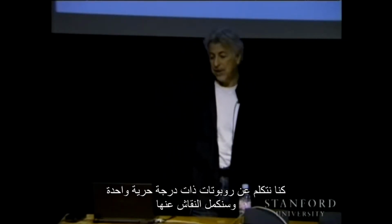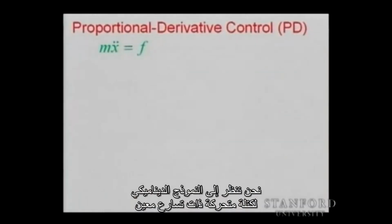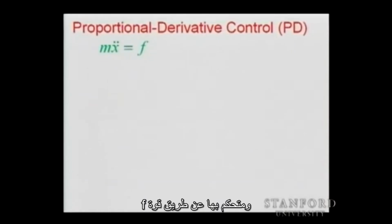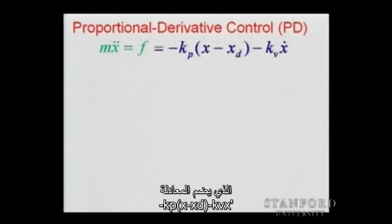So we are looking at the dynamic model of a mass moving at some acceleration x double dot and controlled by a force F. The control of this robot is done through this proportional derivative controller involving minus kp (x minus x desired) and minus kv x dot.